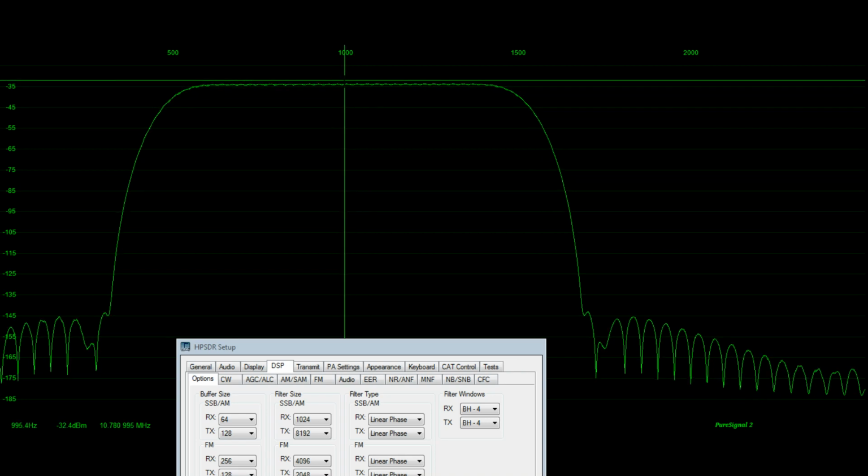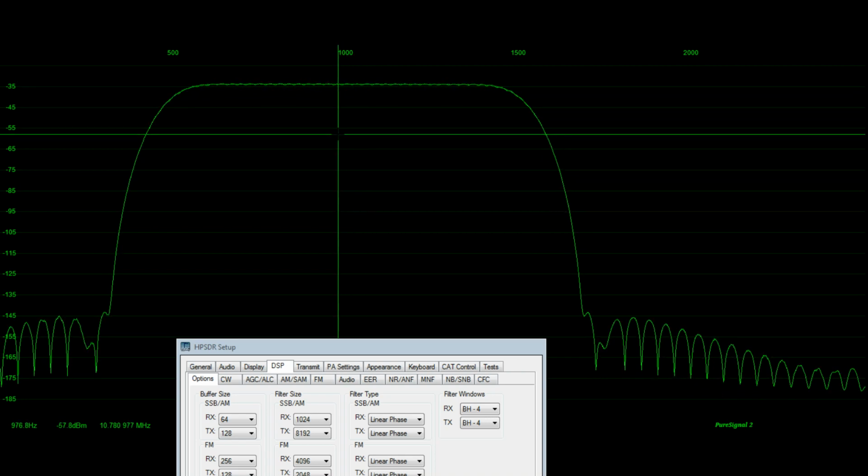So when we talk about measuring a filter and we talk about a shape factor of a filter, classically I've always measured filters by the -6 and the -60 dB bandwidth points, and then dividing the -60 dB value into the -6 dB value to give us a calculated number that can be expressed on how the skirts of the filter actually respond to bandwidth and frequency.